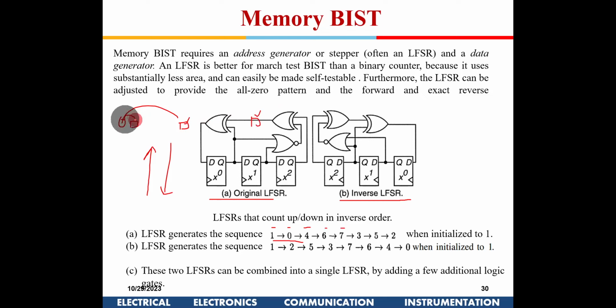Okay, increasing, right? So this cell is not pure binary because I am doing parallel testing. This we saw in our memory days. Like if I have a memory from 1 to 100, I do the testing of 1, then 5, and then 11, I go like that, and then I come back to 2, because the input data pattern required for 1, 5, 11 will be the same. Then I change the data, and then I go to 2, 6, 8.